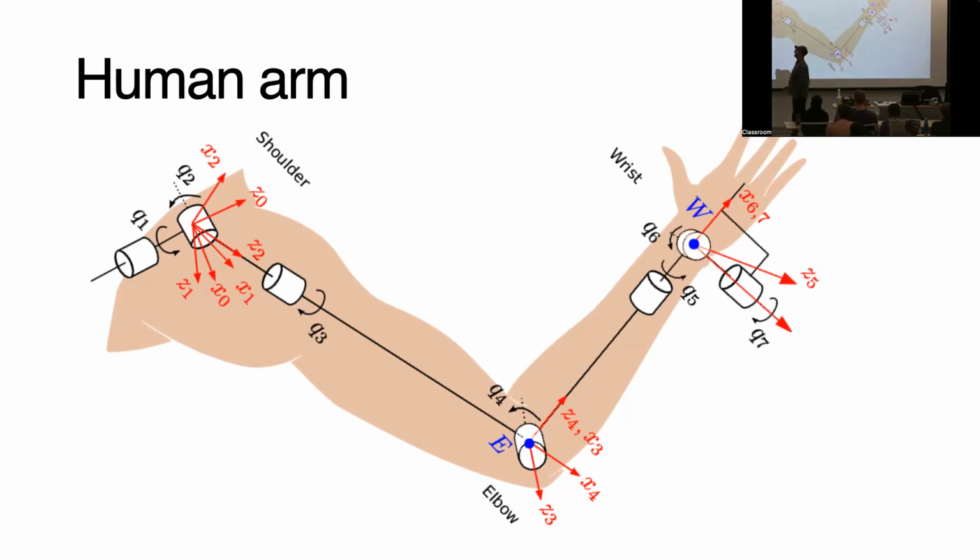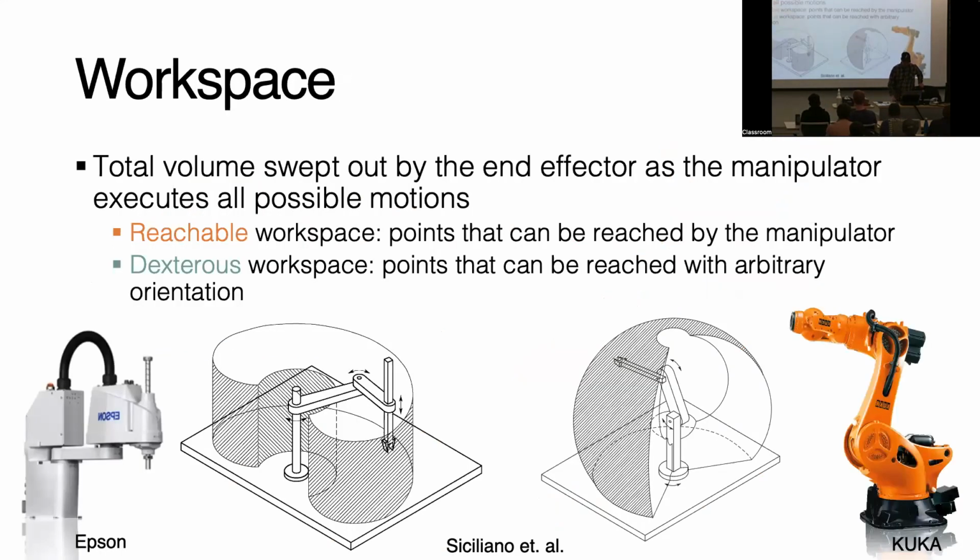And so we're actually able to choose how we move, how we produce the same motion. I can rotate something this way, or I can also do it by rotating my shoulder or something like that. Plus, in addition to that, we have the degrees of freedom that our body gives. So I can move the base frame around by moving my legs, by moving my waist, that sort of thing, okay? So we are fully kinematically redundant, okay?